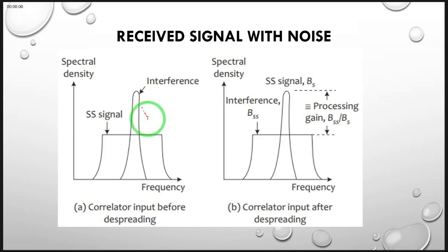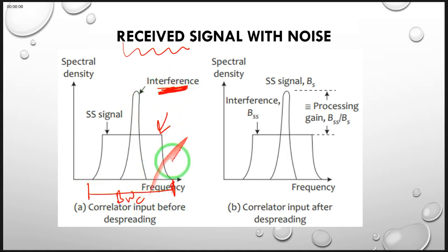And we have also now seen that from the transmitter, we are transmitting this spread spectrum signal that has a bandwidth of BWC, but along the channel some interference may be introduced, and therefore at the receiver we may not be able to recover our spread spectrum signal correctly. So what we need is to be able to remove this interference. So when we multiply our spread spectrum signal with our spreading code at the receiver, another spreading happens.